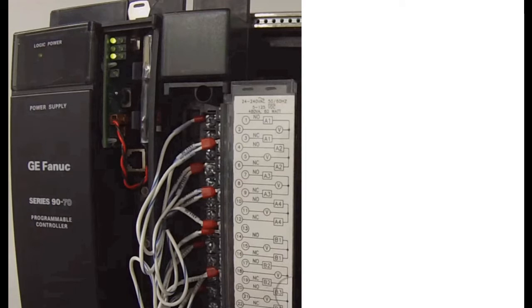When dealing with relay type output modules, keep in mind that some of the output relays may be configured as normally open and the other ones as normally closed. Therefore, the normally closed should read shorted whenever the system is de-energized, and they should open whenever the associated indicating light turns on. Let me repeat that. In this scenario, number 3 is normally closed. When its associated light is on, this contact should open and not conduct.